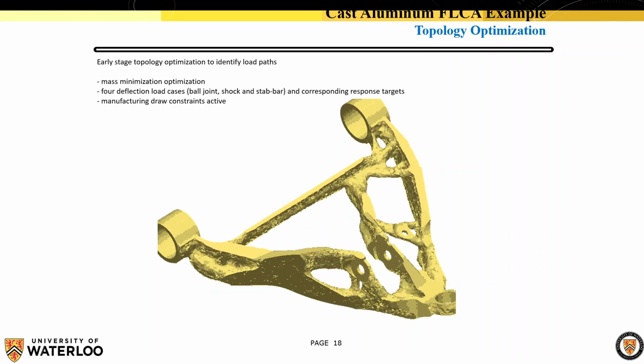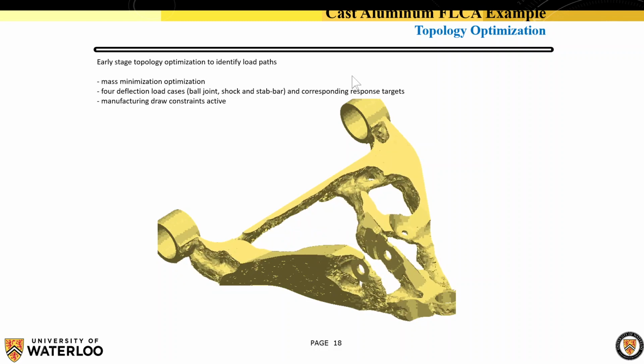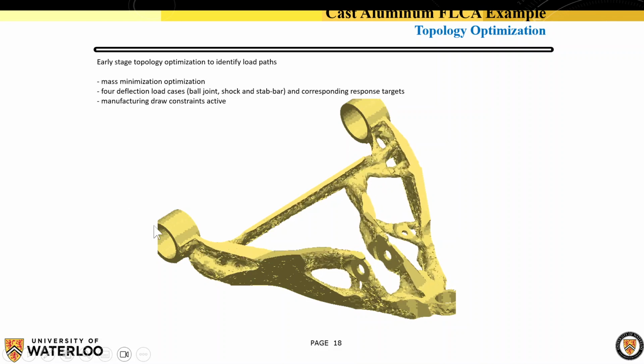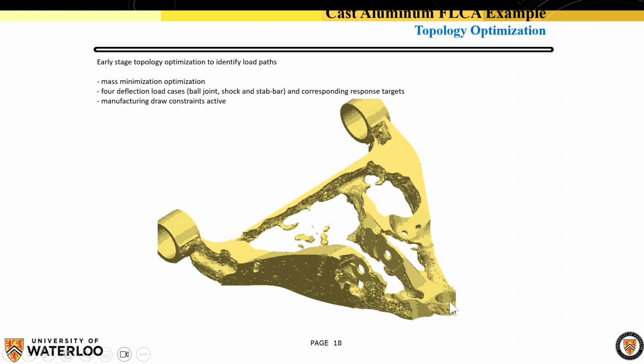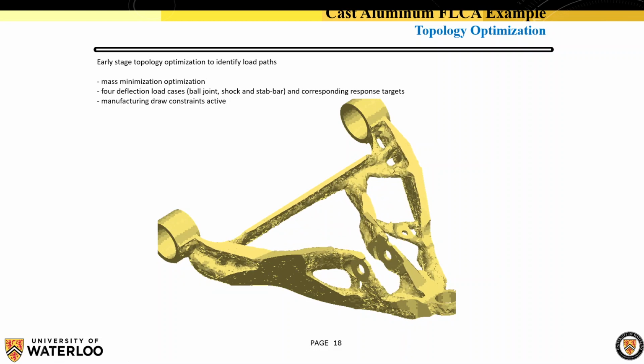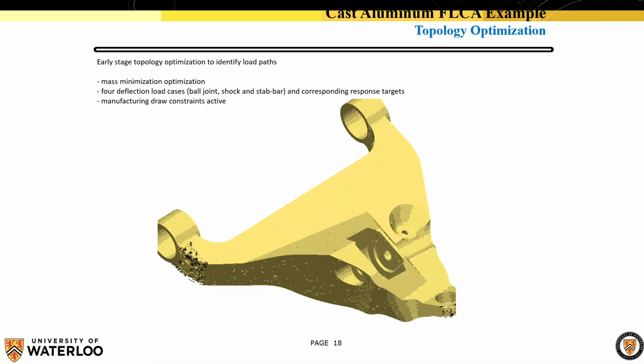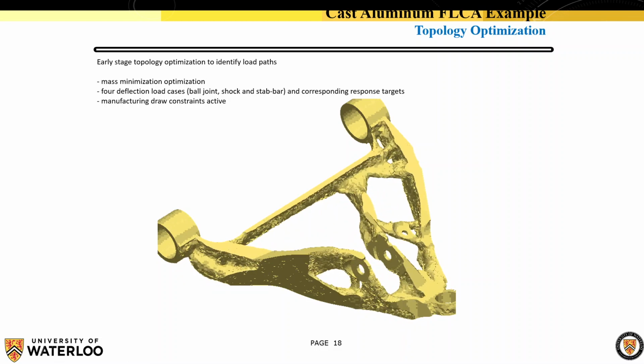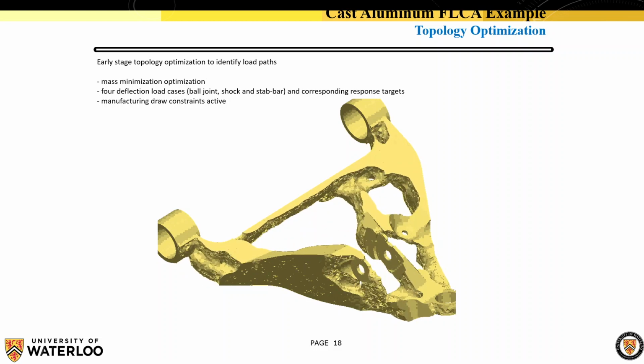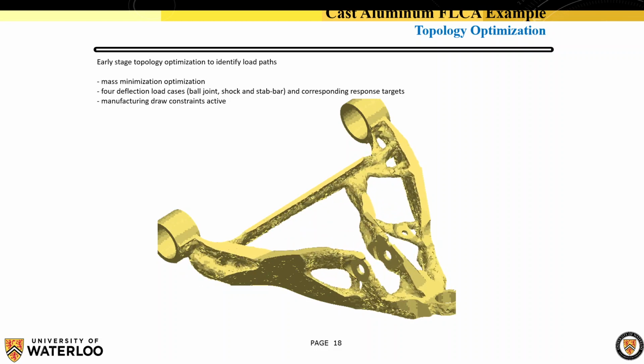Parts that interface with other parts of the design that you don't want to change. So you can see here the 3 locations where it's touching other components. Those are not evolving over time, but you can see the algorithm will iterate and look at areas with low stress, and it will remove them or vary the density.